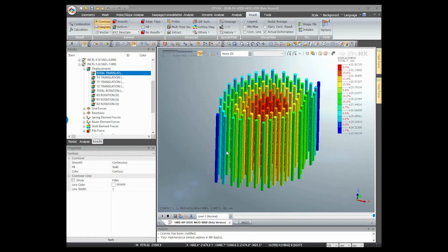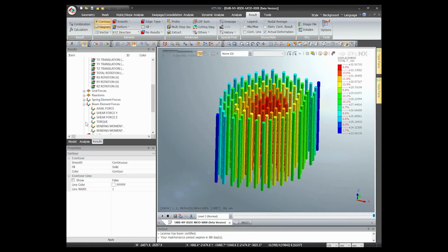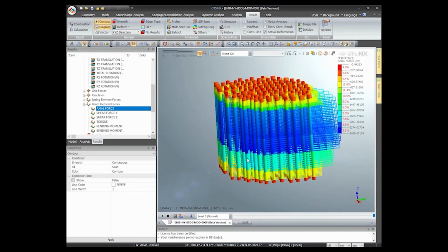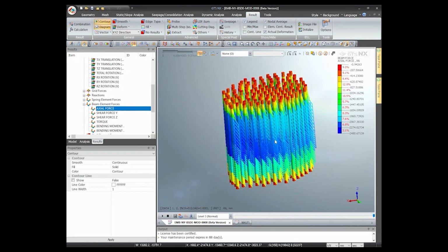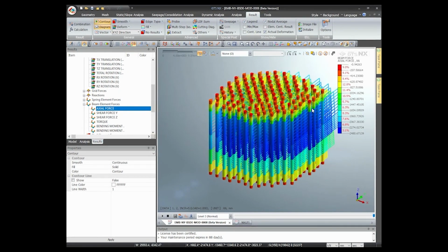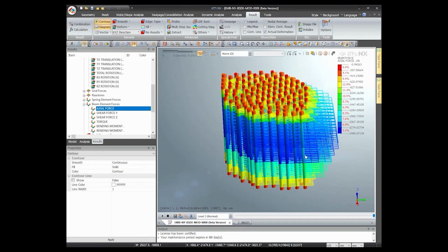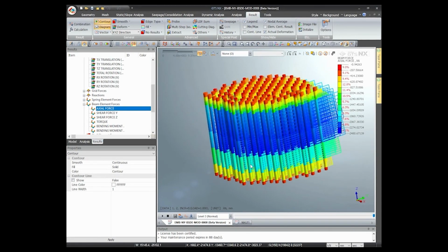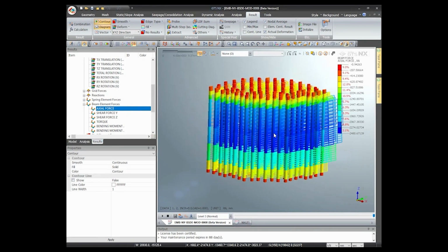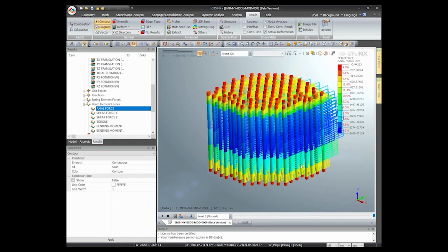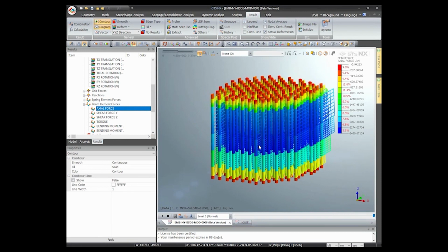So taking a look at the results of axial forces in our piles, as I've said before about extracting those values, we can extract the value of each pile. So these values can be copied from MIDAS Gen and pasted to a spreadsheet in Microsoft Excel. So there we can calculate the spring and easily send it to a structural colleague.